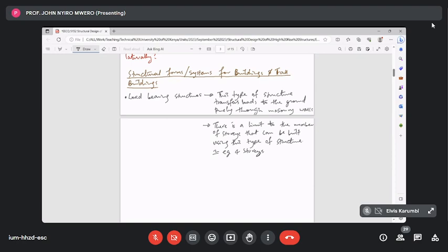Now, coral block is very weak. It's a very weak stone. You can actually break it with your hand like this. If you do that, it just breaks. Generally, when you are doing a structural wall using masonry, there are minimum requirements for the strength of that masonry. I'm sure you were taken through this in some detail when you were taught design of masonry structures.